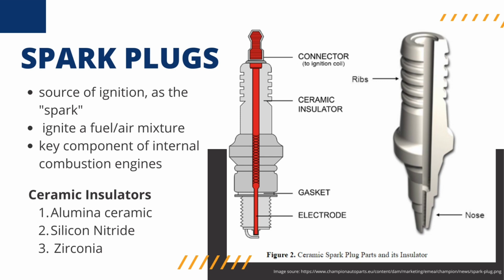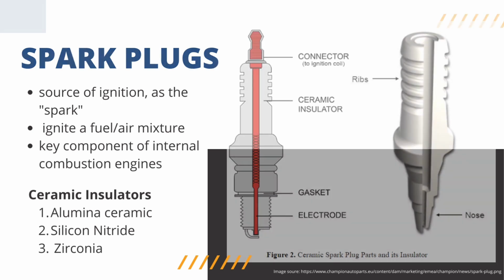So these ceramic insulators prevent high voltage from shorting to the ground, and they remove heat from the combustion chamber. The insulators used in modern spark plugs are typically made of advanced ceramics such as alumina ceramics, silicon nitride, and zirconia.